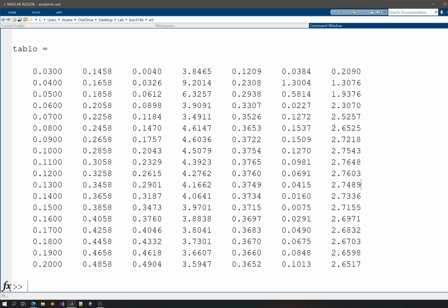Now, I might choose one of these, but how can I combine these indicators so that I have just one indicator that tells me the quality, and I will have a certain weight for each specification. So maybe I'm interested in 50%, 50% in terms of the indicators, which means that the amount of error in settling time should be equal to the amount of error in the overshoot. So everything is equal. So this will be a 50-50 situation here.